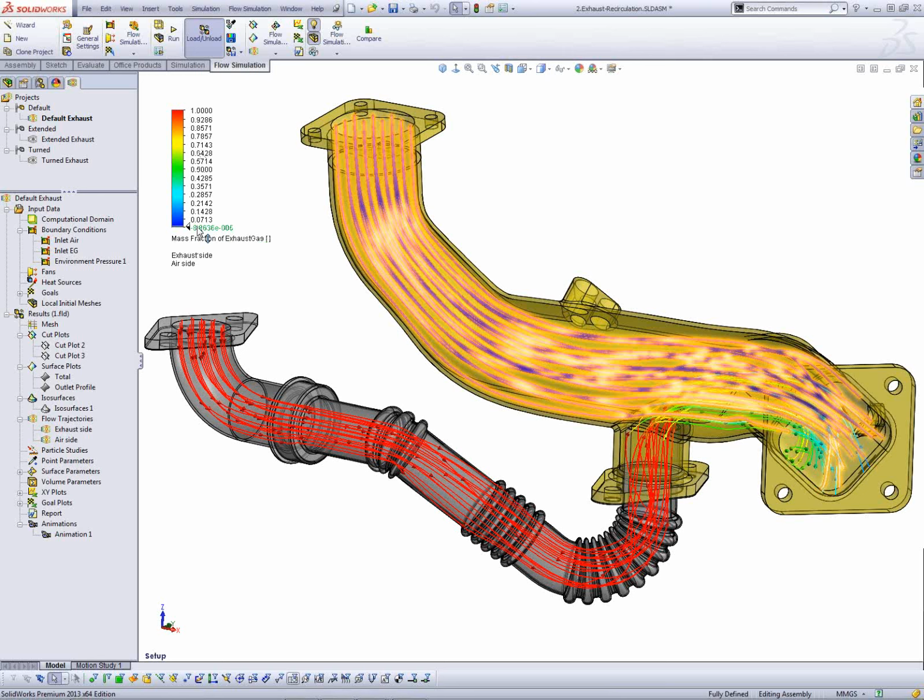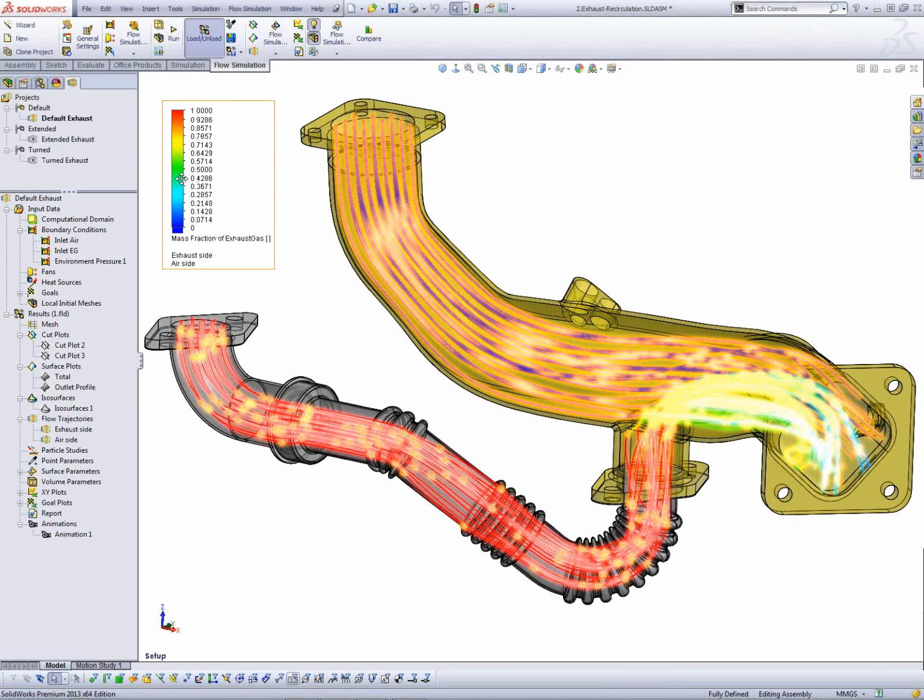You're probably aware of the ability to change the range of values shown here. We can either drag the slider at the lower and upper ends, or we can use icons in here that represent different values. The left icon would represent the minimum value for the entire model. The right icon would represent the value associated with this particular plot that we're viewing. I'm just going to manually shift that down to a value of 0. And for the upper bar, we have a value of 1. So we get a good 0 to 1 range there.